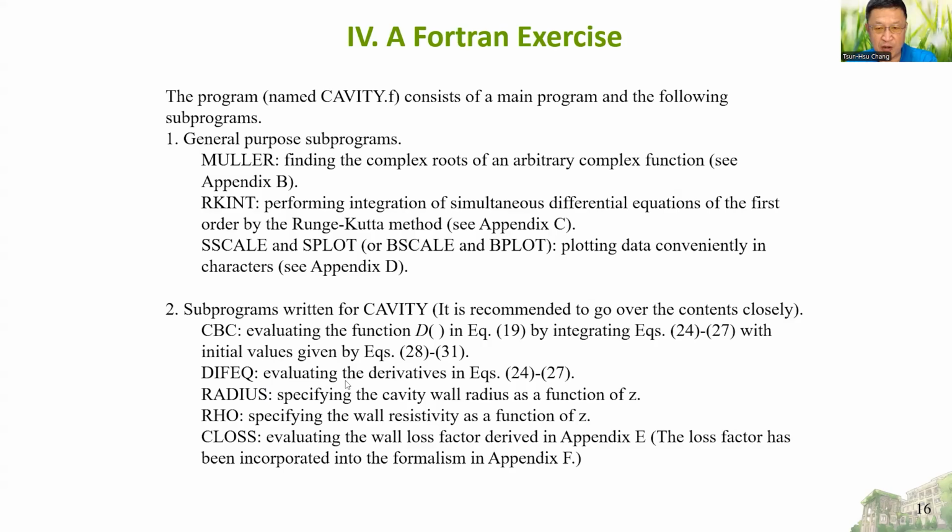Differential equation: evaluate the derivatives of the four equations. Radius: specify the cavity wall radius as a function of z. Rho: specify the wall resistivity as a function of z. So just specify the value.